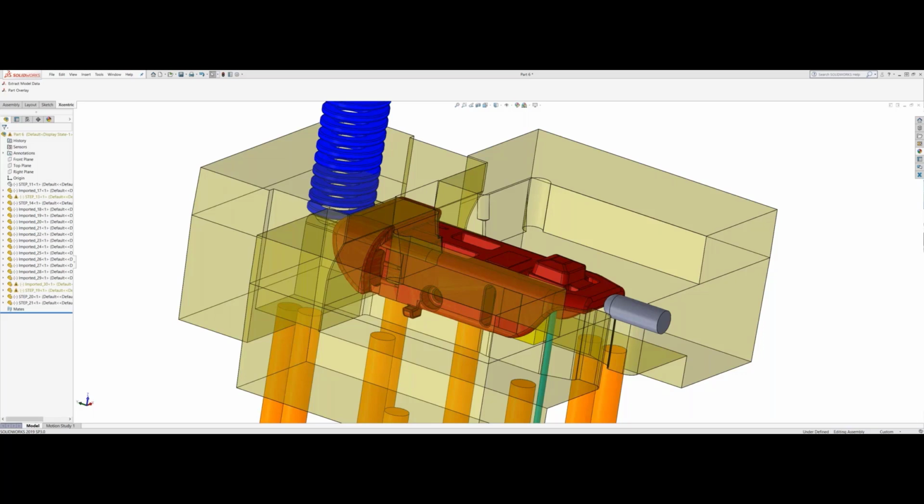It's easier that way. It's cheaper than going to a pre-colored, but it can lead to some issues. You may get swirling, much bigger parts. You can see some flow, uneven part to part coloring. So what we do is we have a swatch or a master plaque, which we use, that's approved by the customer, and that's what we use to check.